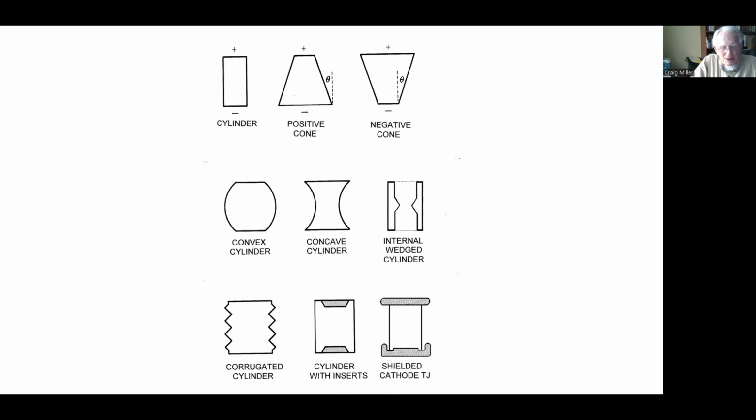So various workers have found that for long insulators, there's an optimum number. For one large insulator they tested, going to 2 or 3 sections improved the hold-off voltage, 3 or 4 was the optimum, and then at 5 or 6 it dropped off again.